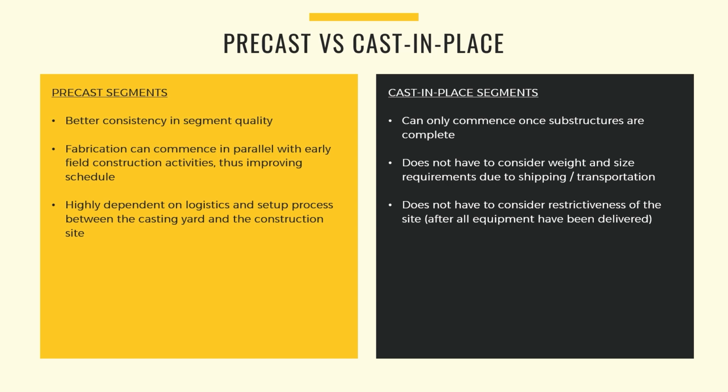For cast-in-place segments, they can only commence once the substructure has been completed. Though, their appeal is that there are no transportation and logistic limitations, so they are preferred when working in restrictive sites or when requiring large or heavy segments.